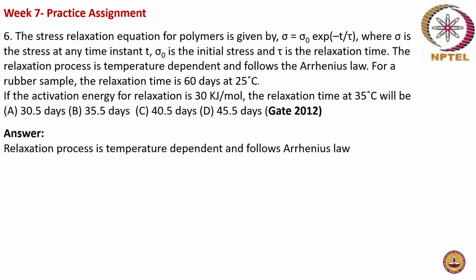If the material is following Arrhenius law, that means it is probably far away from the glass transition. Otherwise, if it is closer to glass transition, then you use the WLF relationship. Now the Arrhenius law is lambda, that is the relaxation time, equal to exponential of activation energy by RT.